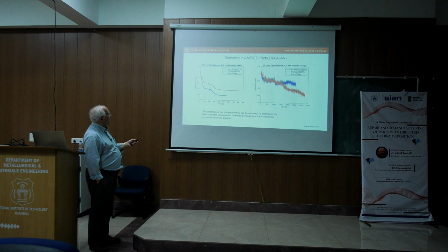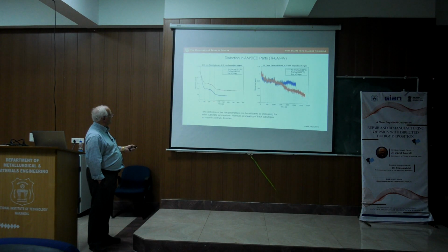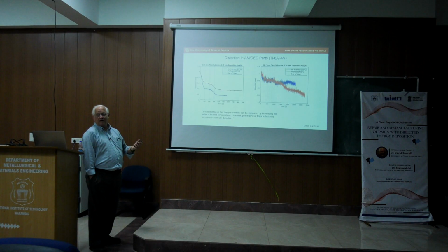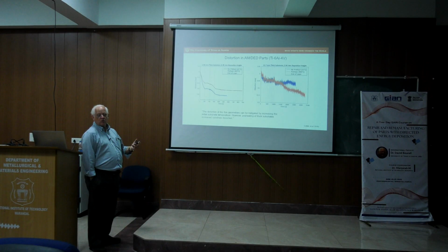If there's no preheat, this shows the distortion, where this is a time plot, and we see that as the build goes on, the distortion actually accumulates. So again, we're starting up here at 0 distortion, and as we move down, in this case with no preheat, we're getting an increasing amount of distortion.